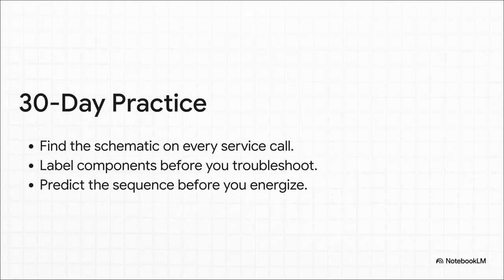Now, mastery isn't built in a day. It takes deliberate practice. So here is your 30-day challenge. On every single service call for the next month, open the panel and find the schematic first. Label the physical components in your head before pulling out your meter. And finally, trace the ladder diagram to predict the exact sequence of operation before you ever restore power.